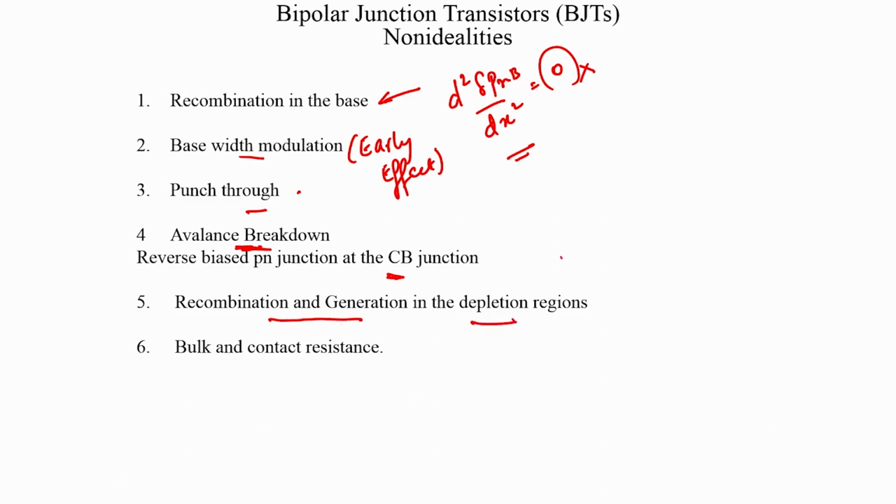That is valid in the case of BJT as well, and we have ignored that. And finally, in the case of the PN junction, when we built the equivalent circuit, we said that there is a depletion capacitance, there is a diode resistance, and then there is the bulk resistance in forward bias operation, which is due to the resistance of the doped regions and the contact, and that is another factor that we have ignored in the case of a BJT.